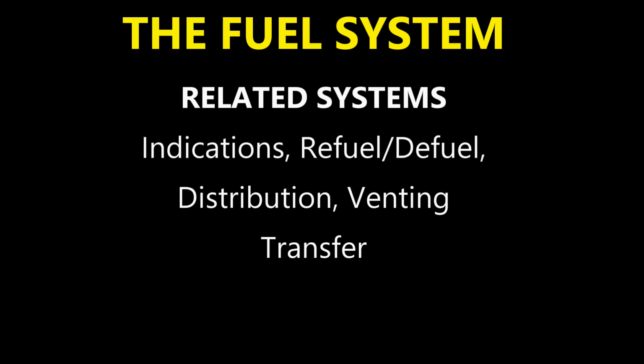So you fill the fuel tanks to their maximum capacity. The aircraft has to be level. There's automatic refueling, and that would be controlled by the fuel quantity indicating computer, your FQIC.